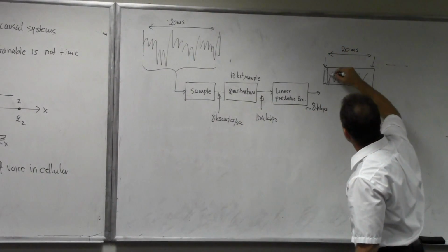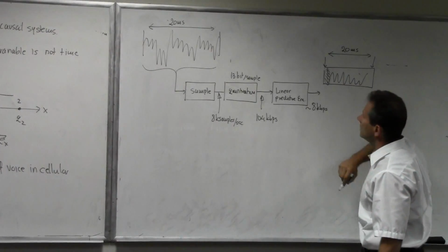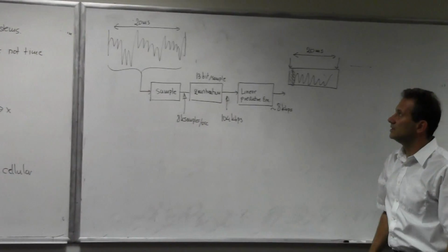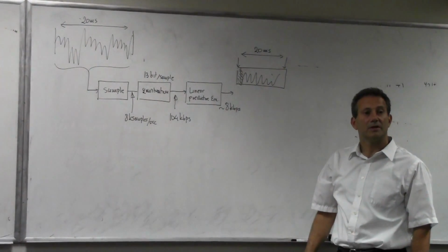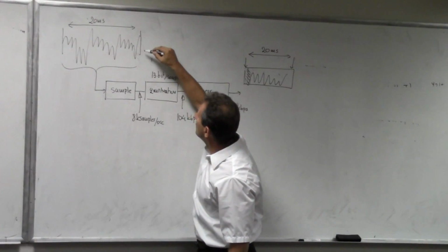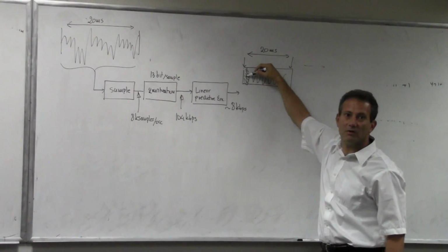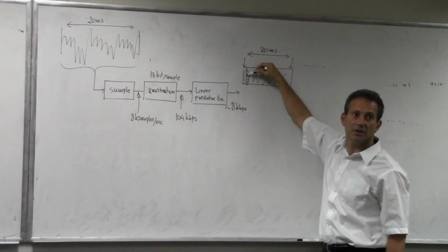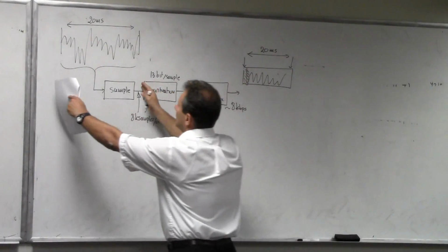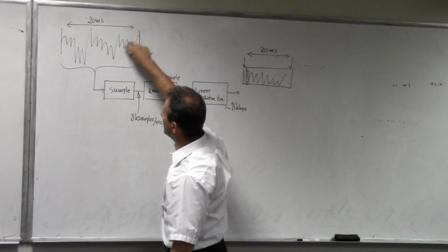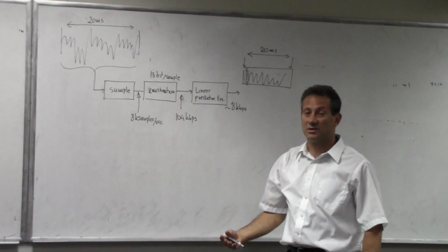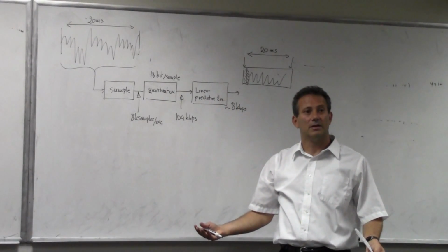But in order to determine what you are going to be sending here, all of the samples that came in this entire 20 millisecond frame participate. So in other words, this sample here contributed to what should be the value of what comes out at this point. So that's a non-causal system. If you try to match this 20 milliseconds to 20 milliseconds, then this one impacted the beginning of this frame. So that's an example of a non-causal system. We're not inventing anything earth-shaking.